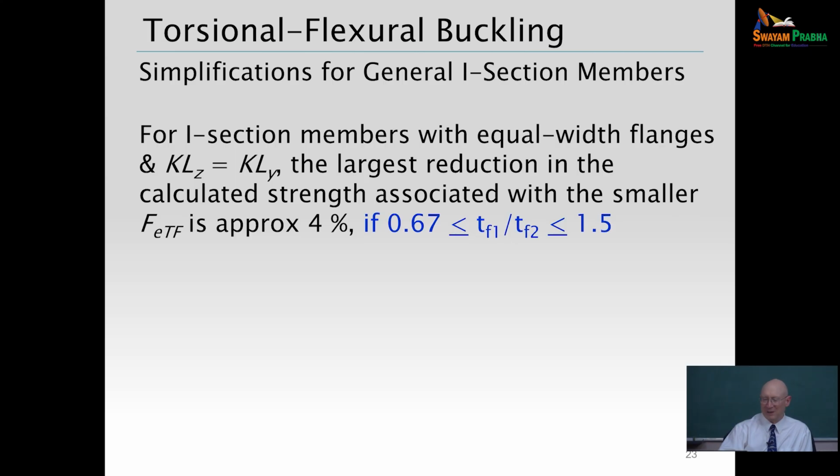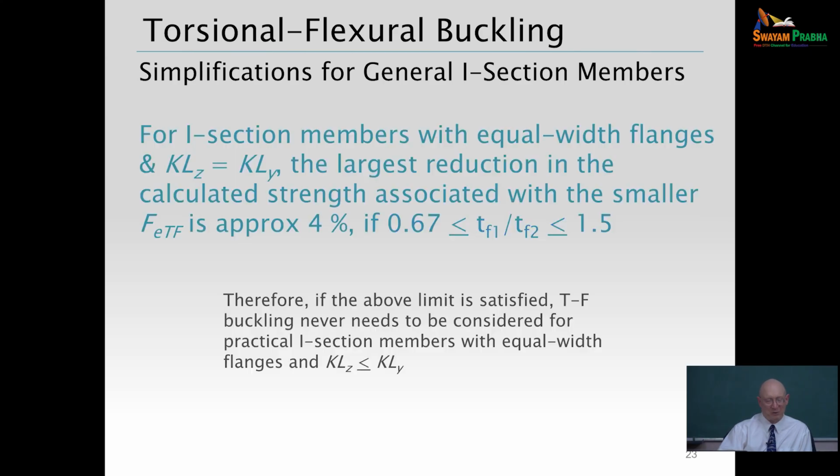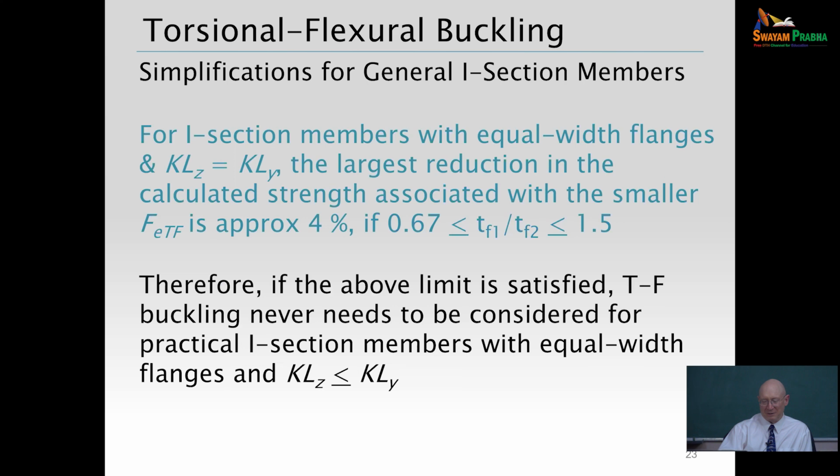But if you have unequal width, forget it. You better calculate the torsional flexural buckling stress. And so that would be a practical recommendation for engineering or industry folk who would like to not have to bother with running the calculations via the torsional flexural buckling formula. Just work with flexural buckling.